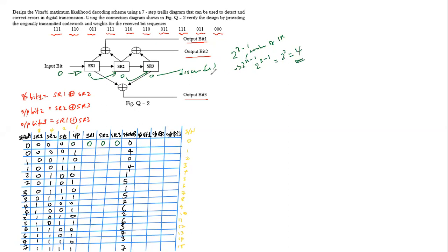But now, we are not designing the regular trellis diagram. We have the regular trellis diagram in the video too. So we are looking at the 7-step trellis. So we want to move 7 steps. Now for us to move 7 steps, it means I have to move from 0 to 1 to 2 to 3 to 4 to 5 to 6 to 7. And if I do that, I'll be somewhere at the middle, since we now have to play with 16 possible code words, okay?